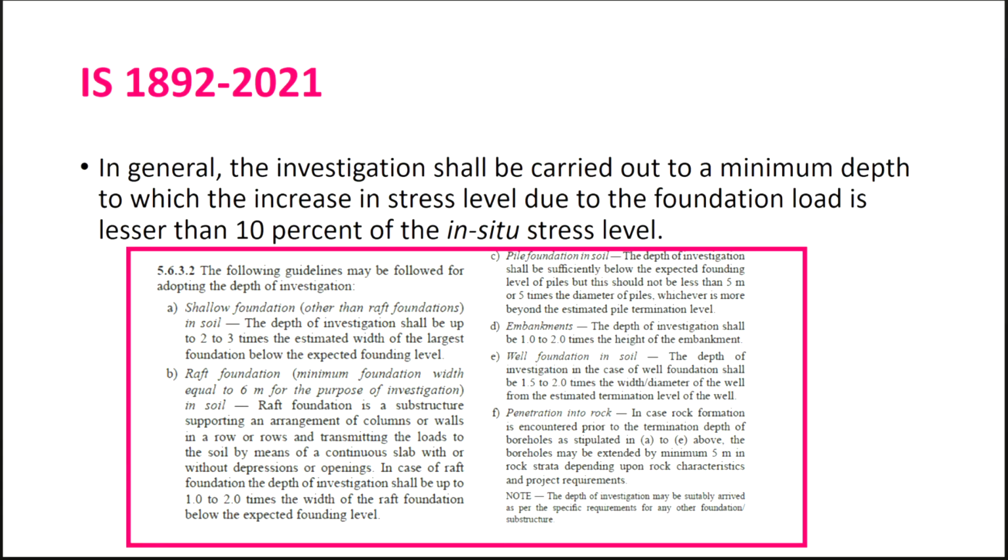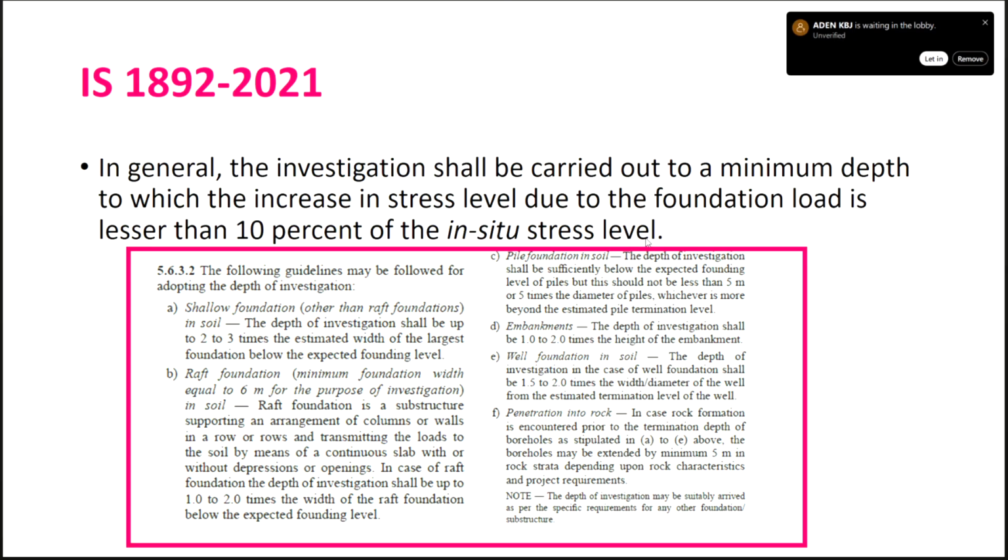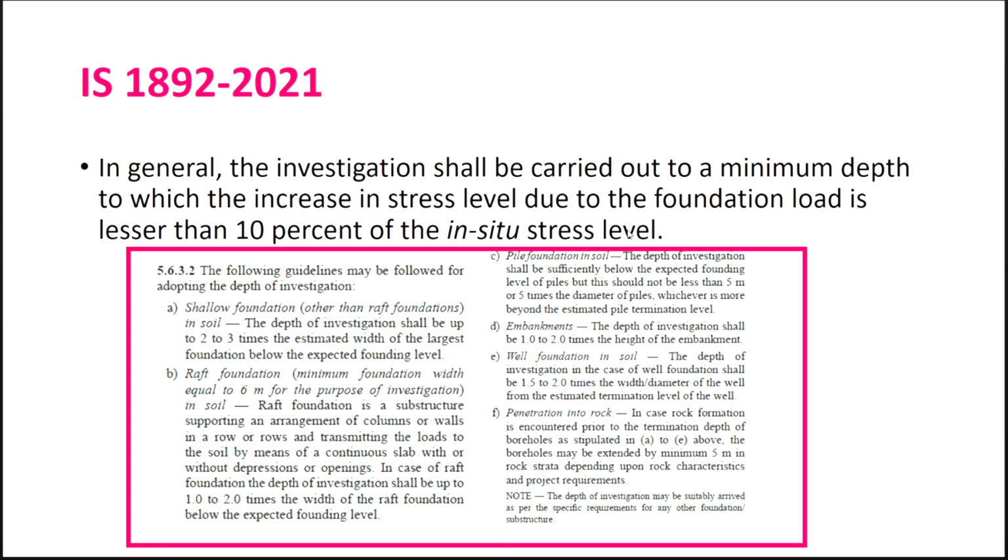Now there are certain things again, minimum depth. Now this was with respect to how many you have to do. Now what should be the depth up to which I should go? If you go by the definition, it is the minimum depth to which the increase in stress level due to the foundation load is less than 10% of the in situ stress level. Now this is a theoretical definition. So I will just show you what they are saying for shallow foundation, raft foundation, pile foundation in soils, well foundation in soils, penetration into the rock, embankment details, a lot of things they have given.